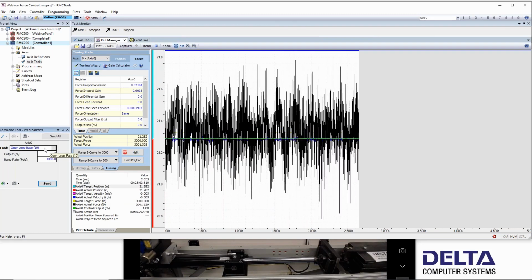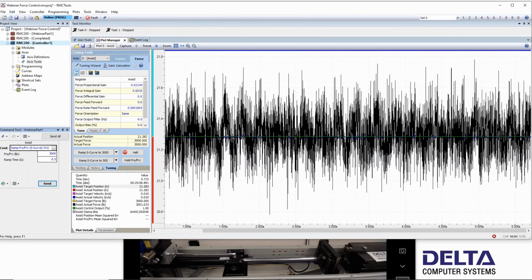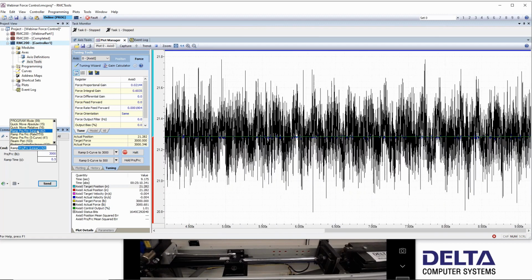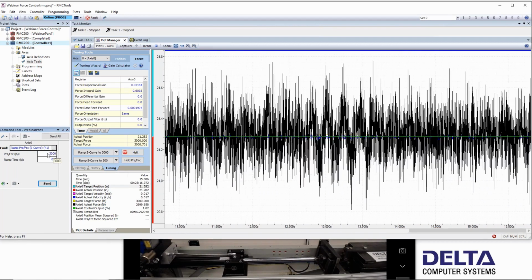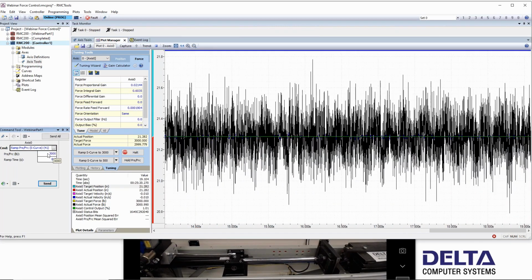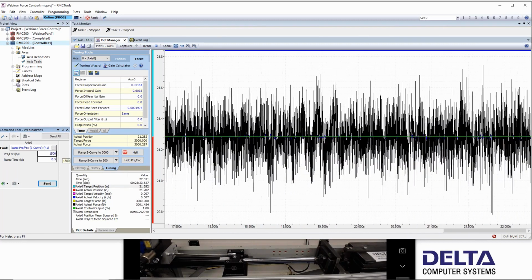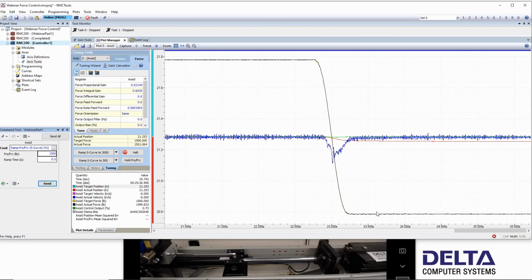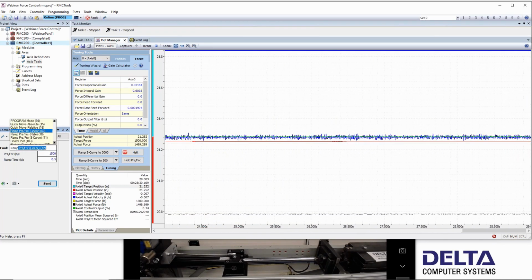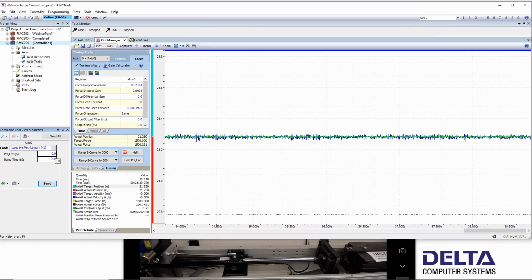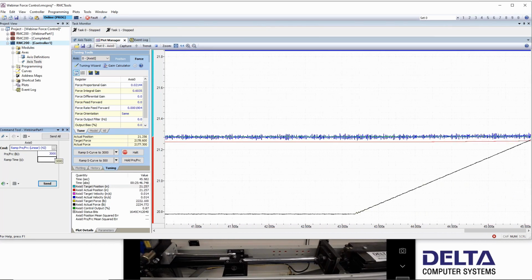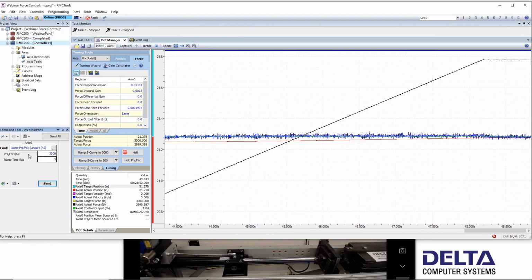So we are now in force control, and if we ramp to pressure force control, I usually prefer the S-curve. Notice that we have the options of linear and S-curve. S-curve gives a smoother change. The linear, with the sharp changes, sometimes can introduce really sharp changes in the control output signal to the valve, and that can cause us problems sometimes. But here I'll ramp down to 1500 PSI. And we also have different types of ramps. We can actually search for those here in the pressure force control. If we do a linear, some kinds of test systems need you to linearly ramp over a long time to a certain pressure. We can certainly do that here.